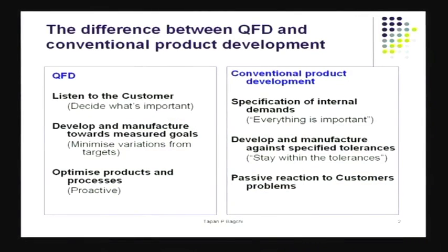Of course, then what we do is, once we have the specs there, we design our manufacturing system. In the conventional approach, we would then say, well, now we have to come in. Perhaps for the cap, we'll be doing injection molding. And the specs are given there, therefore that is going to give us the size of the holes and everything else. When I design that little die that is going to be casting these little plastic caps, that will come about only after I've given the specs for this.